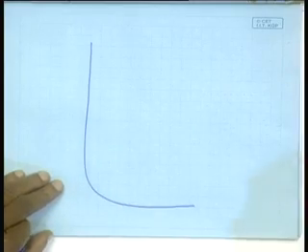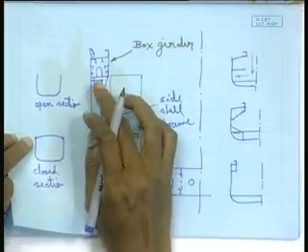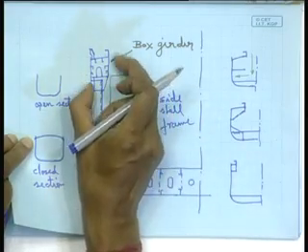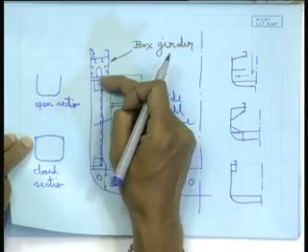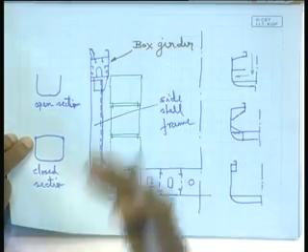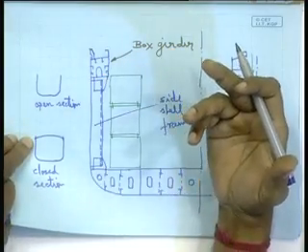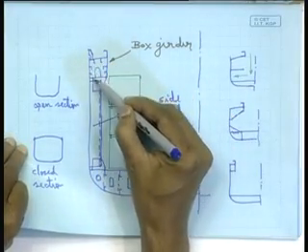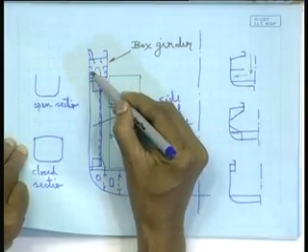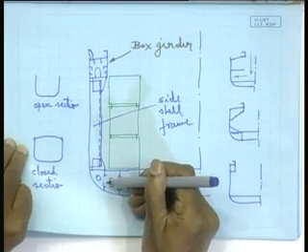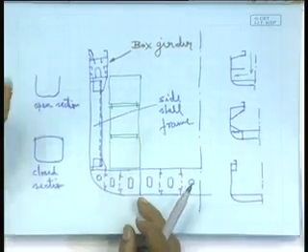That means this kind of box girder arrangement was becoming inadequate, because here your heavy construction is there only at the top. At the middle part or just below that you have transverses, but still it was becoming inadequate. So, the idea became that instead of keeping the box only located at the top, let it be continued till the bottom, then automatically your strength becomes much more.